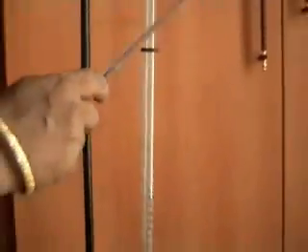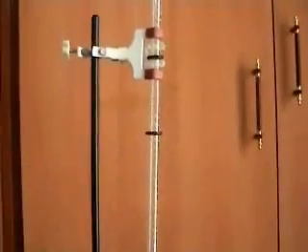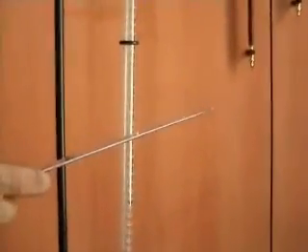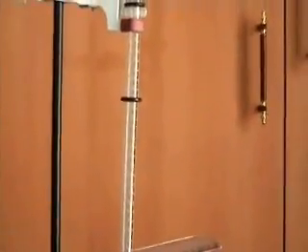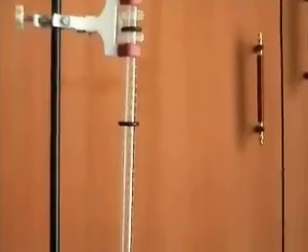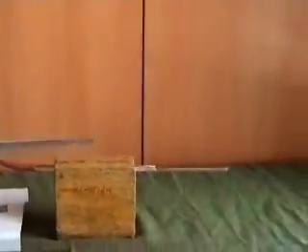The principle here is that the height of 40 from the axis of the capillary tube is different from the height of 45 from the axis of the capillary tube, etc. So we are calculating the time for a 5 cc flow of liquid, but the heights of 40 and 45 are different. So when we calculate the time, what height do we have to take? We have to take the average height.